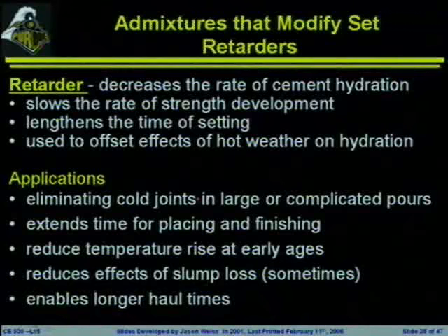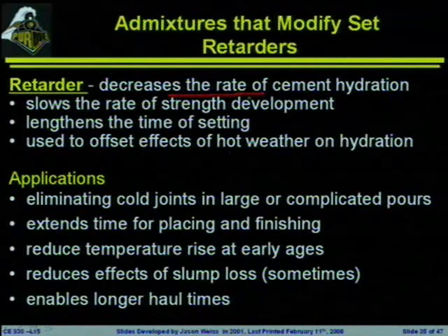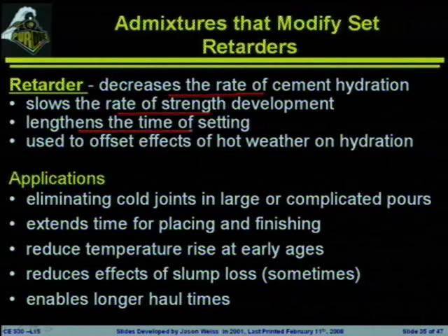If accelerators were there to pick up the rate of reaction, retarders are there to decrease the rate of cement hydration. Obviously, we're going to slow the strength development of the system. If it's too hot, it can lengthen the time of setting, and can be used to offset the effects of hot weather on hydration. Some of the applications: we want to try to eliminate cold joints. Here you're talking about concrete that may be placed and starts to set up. The next batch of concrete comes and is cast on top of it. The two don't really match up or mesh together.